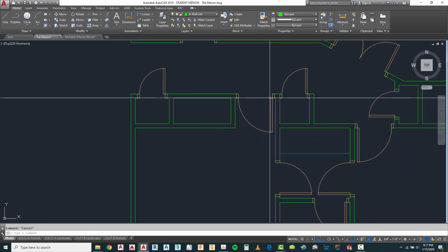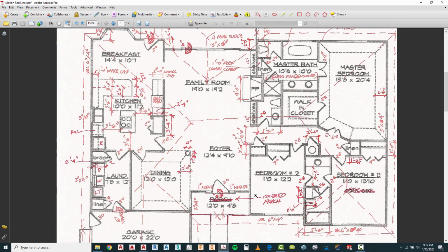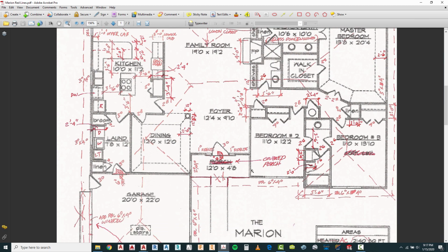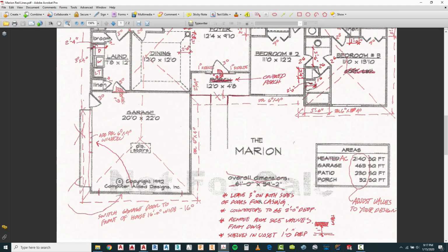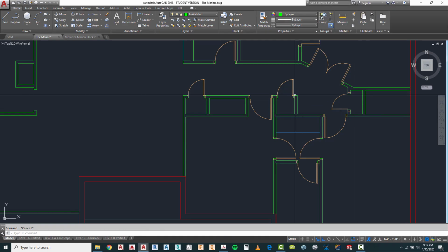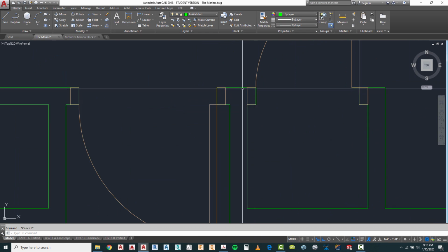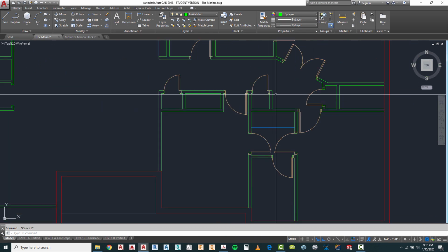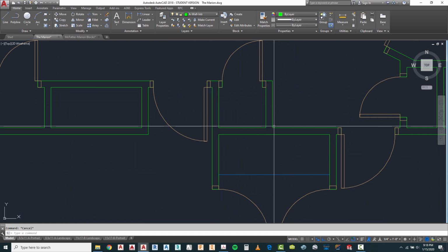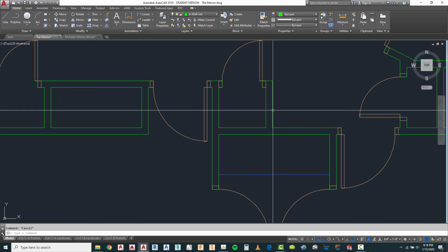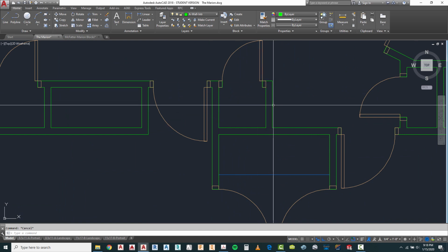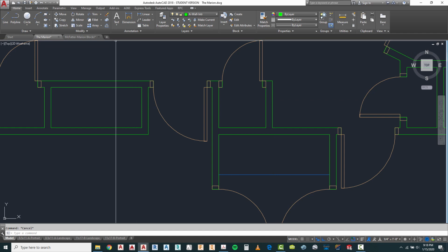Now, one of the requisites that I indicated here was to leave 3 inches on both sides of the door. And if you take a look at our condition in here, this is a closet where I only end up having 2 inches available here. Now I could stretch this door over about 4 inches, and that'll give me the additional room. So let's go ahead and do that.